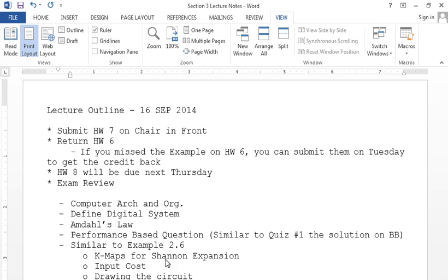VHDL. Yep, so VHDL. What exactly would I be asking about the VHDL? Library. Make sure you include the 2 libraries. What are the 2 things that you have to include at the top of every file? Library IEEE, and then use IEEE.std_logic_1164.all, right? 754? No, use 1164. If you put 754, you lose points.